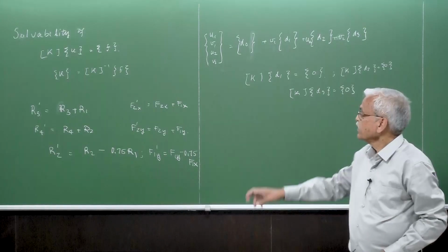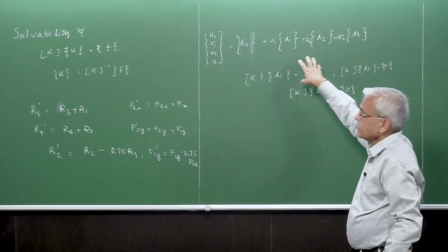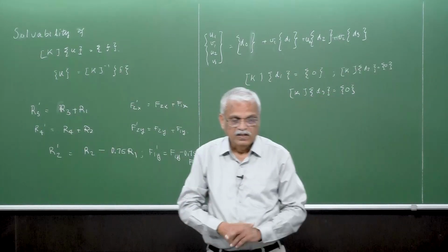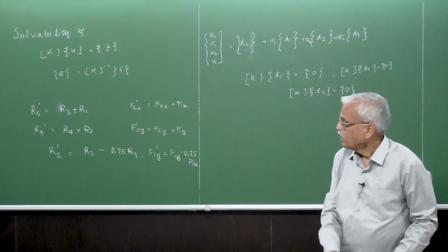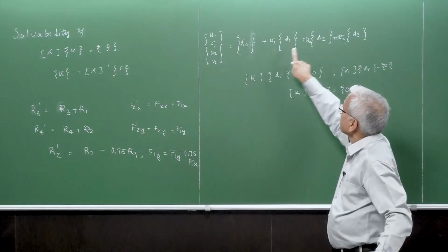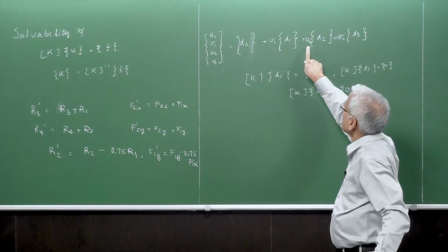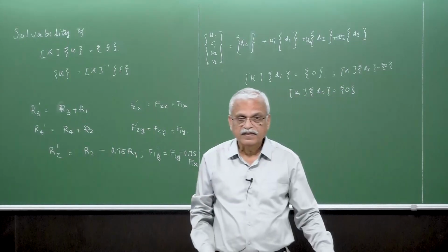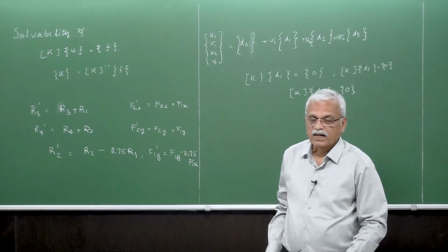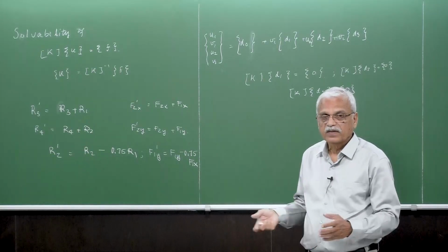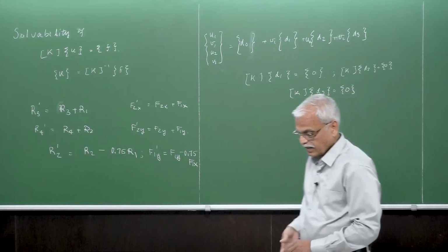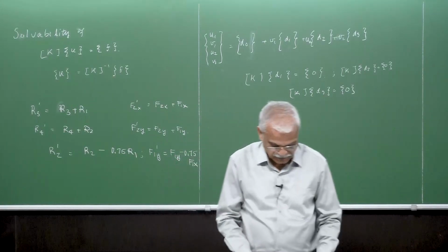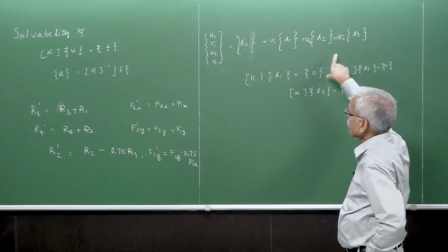Okay, so that means that you can devise another three vectors here which also have rigid body modes. What essentially this means is that to get a solution here, you have to arbitrarily give V1, U2 or V2, or for that matter, any other three configurations which will fix the rigid body. So that means that you have to apply the displacement configuration. Okay, so that way we have the total solution here.